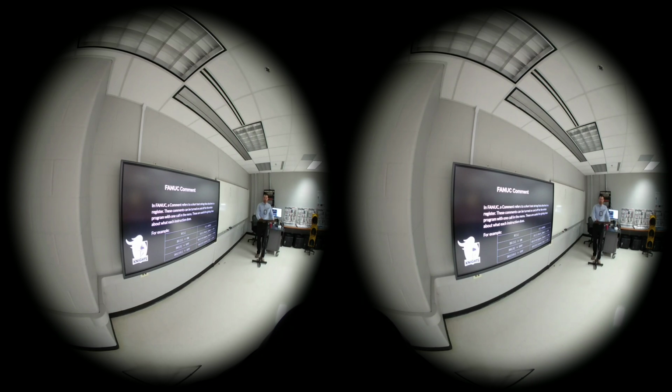The digital input might be something like, on our educational cell, we have the door that will open, and that's a digital input to the machine. And so you can have that read out that the door's open, and that's why it's preventing you from proceeding, because you need to close the door. Likewise with having a gripper, a digital output could be used to open and close a gripper, and it actually gives a context, right? It gives a meaning, because this gives you no hints or no clues. And likewise with the laser.